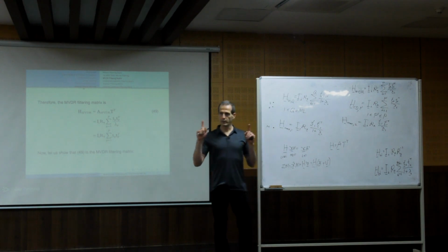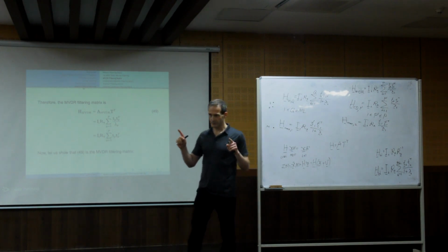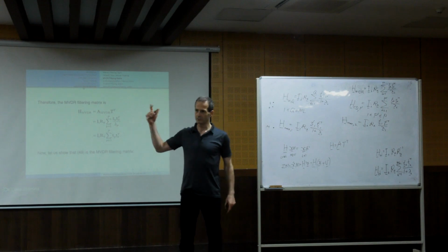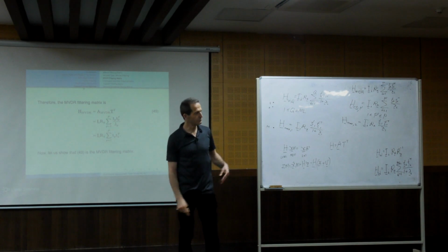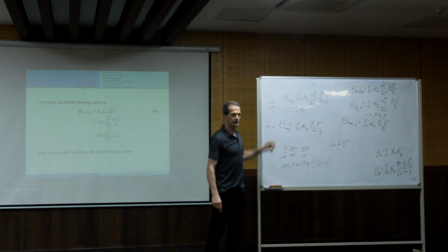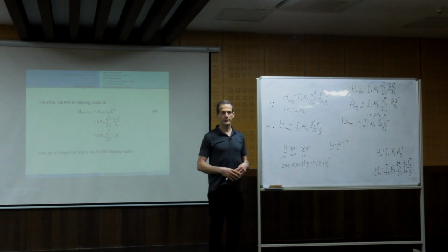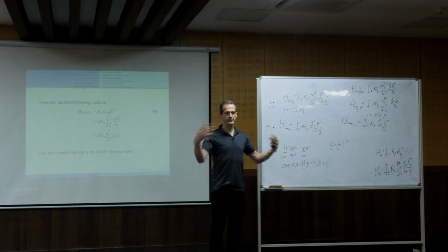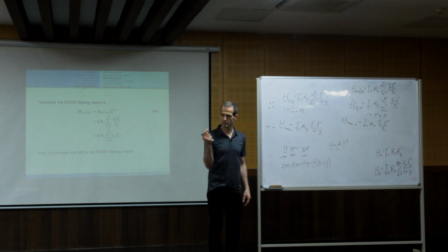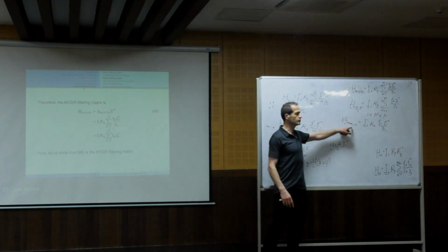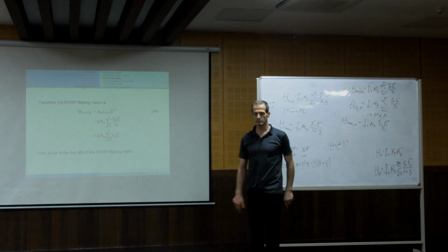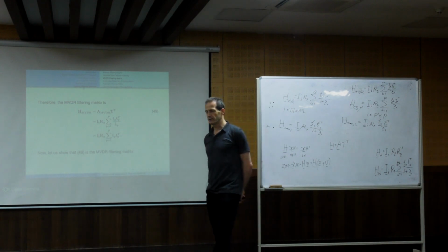So with the maximum SNR filters, what we showed in the time domain and frequency domain, also here in the multi-channel maximum SNR, you have many solutions. So you have a degree of freedom to choose which one you choose. If you care more about the MSE, you will choose this. If you care more about distortion, you will choose this. So it's flexible. See?